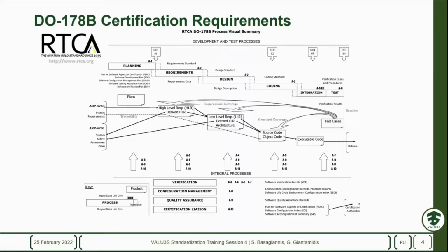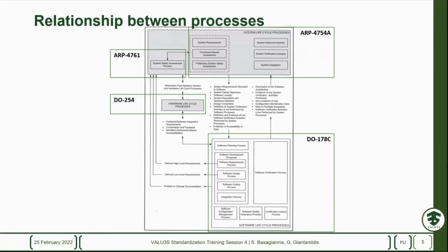And the coverage is another part of the story, which has to be shown in, for example, MCDC coverage for DAL A requirements, but it could be relaxed later on for less critical requirements.